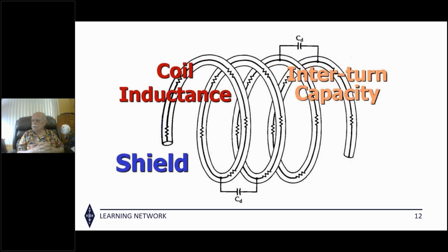Okay, no problem. Next, can the Balun be over an aluminum or other non-ferrous metal such as a boom or a mast? Well, you say, could you wind, or you mean can you wind it on a piece of aluminum? I think he means can you wind the Balun, the big ugly Balun, and then run a mast through the middle of it? I think that's what he's asking. And yes, that works reasonably well. It will change the choking a bit and change the inductance of the coil, but I think that can be done. That's quite a variable question, of course, a lot of variables in that equation. But I think you could easily wind a 4-inch ugly Balun and run the mast through it coaxially. I don't think that would hurt you.